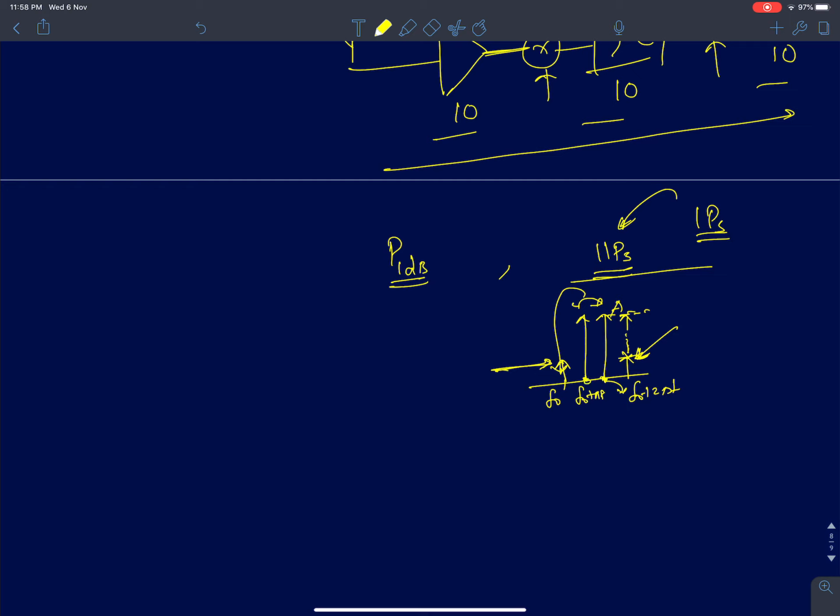We just fed two signals of amplitude A, and then we measured the strength of the intermodulation component, which is the IM component. And again, these two arise only because of the third harmonic. If there was only second harmonic, you wouldn't get these intermodulation terms. They arise only because of the presence of a third order nonlinearity. When I said the nonlinearity is modeled like this: k1x minus k3x cube.